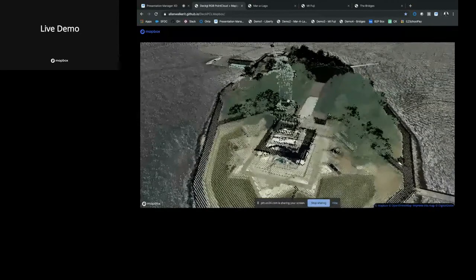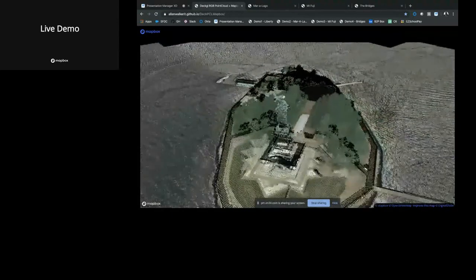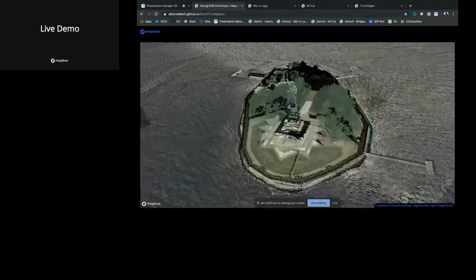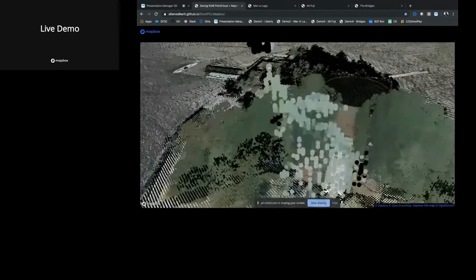And with this, we can get some really crazy level of detail from taking LIDAR data from the NOAA elevation website, and then we take the imagery, which is GeoTIFF, and we use a tool called GDAL to XYZ, which what we're doing is basically for every single point, so just one of these, what we're doing is we take the latitude and the longitude as X and Y, and then the Z is the height in meters.